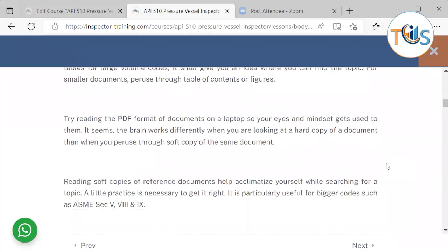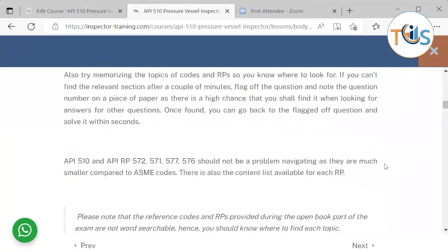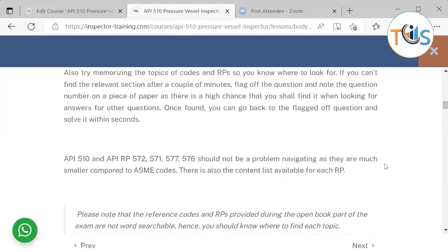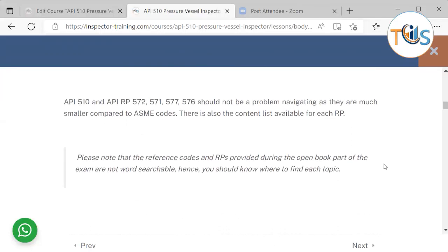And then the other thing is you always need to read the PDF document. Obviously nowadays nobody has a hard copy anyway, but you can highlight the PDF document, and your eyes get used to which page you can go to in ASME Section 9 to determine the qualification range, say for a pipe diameter or thickness, etc. So it's all about practice, flagging, tabbing, highlighting, and you get the hang of it. It's something that you need to learn, how to use the codes and where to look.